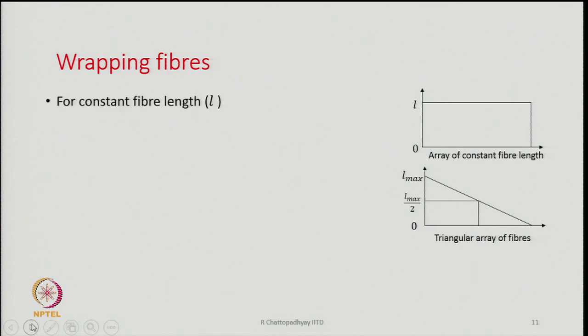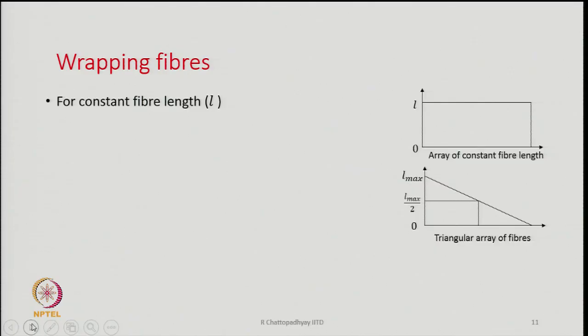Wrapper fibers, we call them sheath fibers also, and some of them will be tightly wrapped and we call them belts. So, we will find many fibers like this. There could be some fibers which are partially forming the sheath fiber and part of it is actually within the yarn core. So, it is buried in the core, one part, the other part is lying on the surface. So, one part is a part of the core and the other part is part of the sheath. This kind of fibers also will be visible.